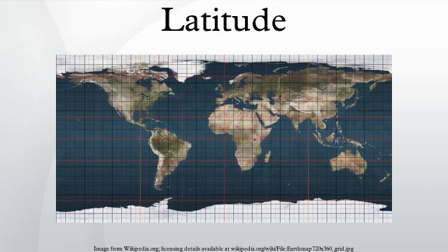The same coordinates on the datum ED 50 define a point on the ground which is 140 m distant from the tower. A web search may produce several different values for the latitude of the tower. The reference ellipsoid is rarely specified.